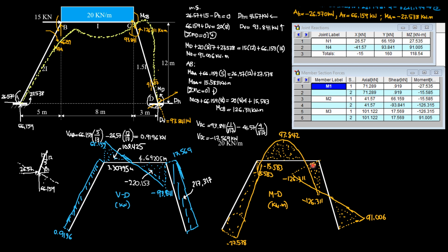and therefore for the elastic curve, we have point of inflection here, point of inflection here, and here. 3 points of inflection. This is negative moment, so it is concave down. This is the upper fiber. So concave down, you look at in that direction. Imagine that's horizontal. So concave down for this portion, concave up for this portion, concave down, concave up. Then negative moment means concave down again. Then negative moment in this portion here is concave down.